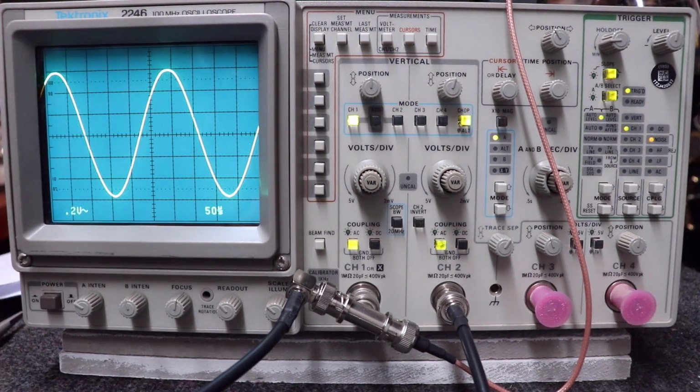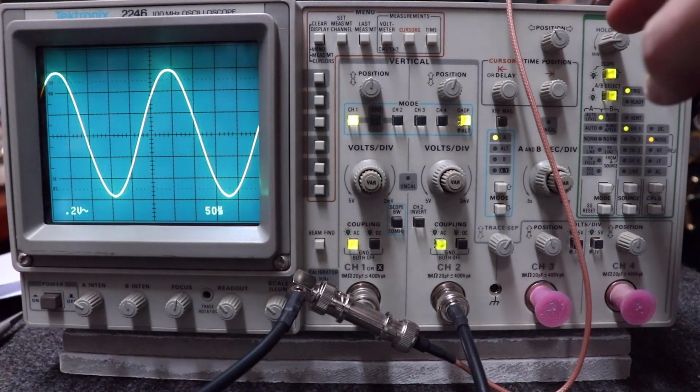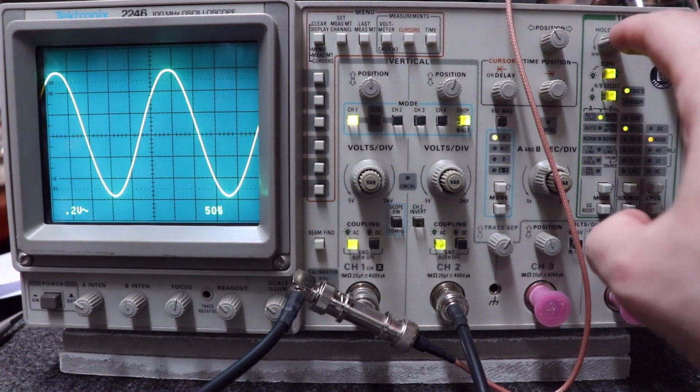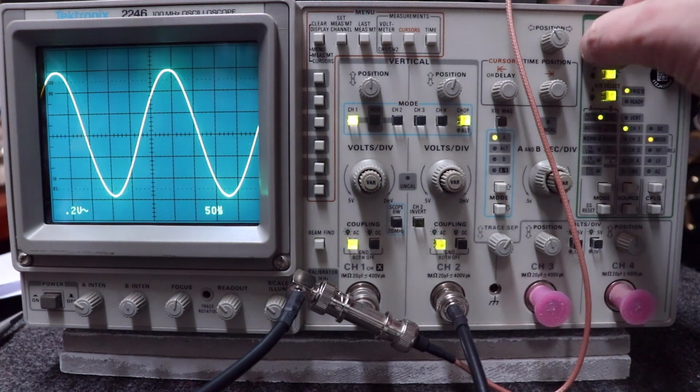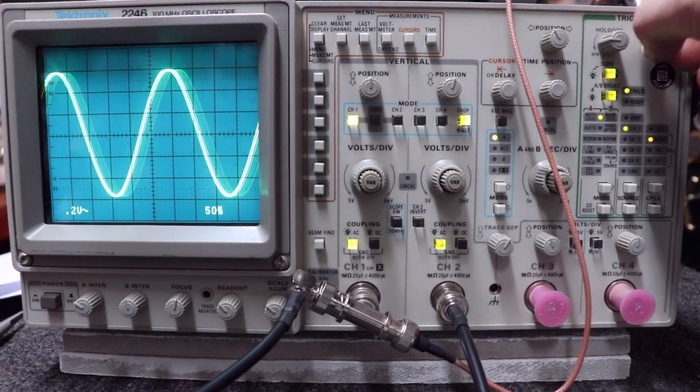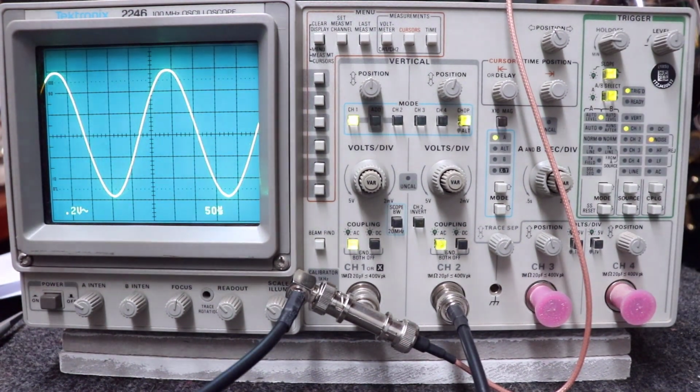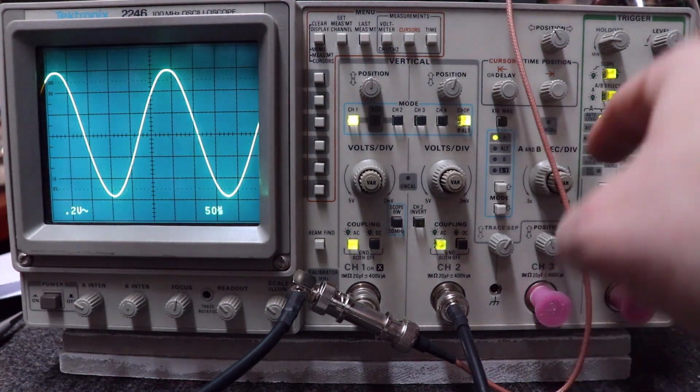sine wave. Now, if I'm actually looking at a real audio wave, which is made up of a lot of frequencies all at one point in time, I may need to play with these trigger things. The good news is these are the only two knobs. You really just have to adjust one and or the other until you get locked on trigger wise. You can't go wrong here.